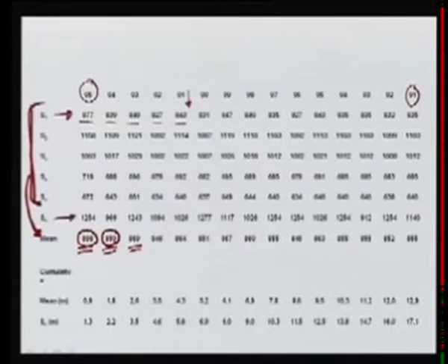This gives us the mean annual precipitation at S6 for each year. Now in double mass curve we do cumulative analysis. So this is the cumulative value. Mean means again stations S1 to S5, and now this is in meters. So this 898 actually becomes about 0.9 meters, and then this is cumulative, so we add the next year.